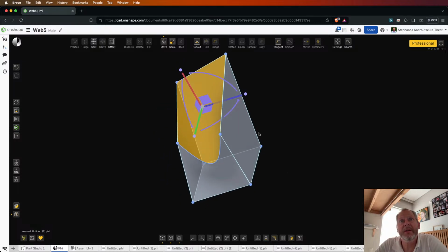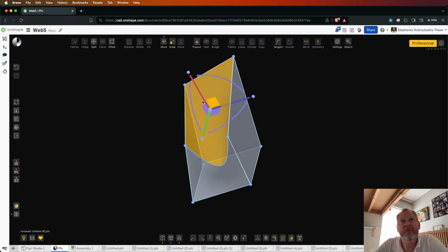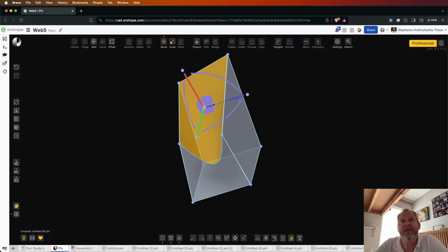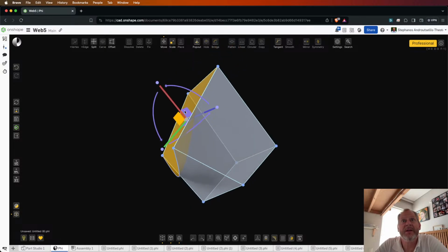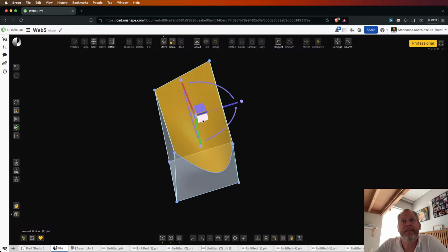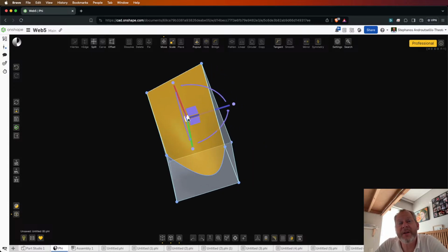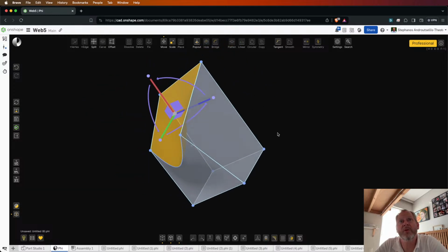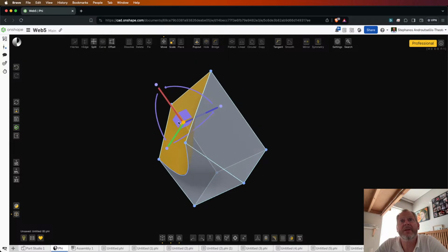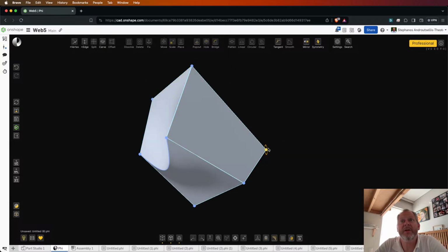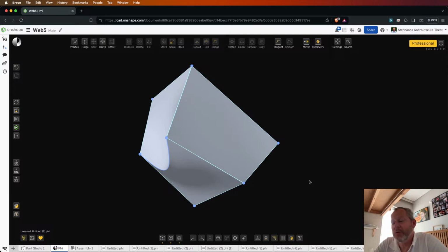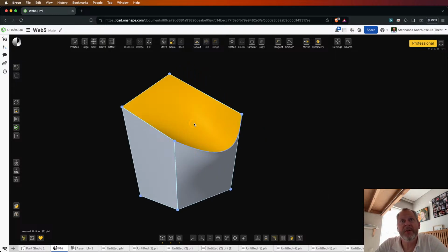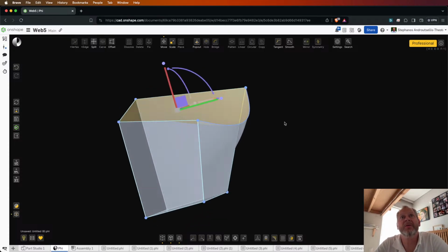Now, we also have 3 little planes here which allow you to move within a plane. So this is within the XY, XZ and YZ planes. And finally there's also a little square exactly at the center which allows for a free move. So no matter what view you are in, this is equivalent to, for example, directly moving a vertex. So these are the main elements of the move manipulator. I'll hit M, which is the shortcut for move, and it's exactly equivalent to clicking on the button.